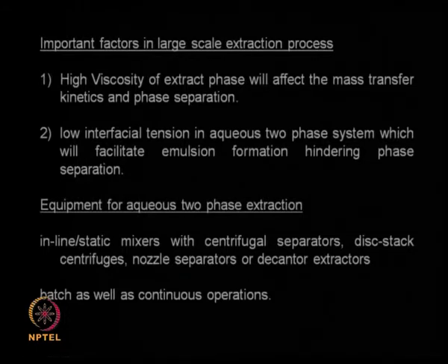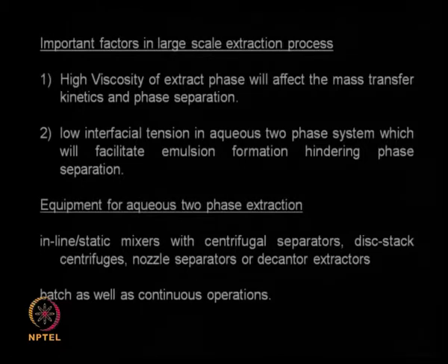So these two important points we need to consider when you are scaling up this type of aqueous two phase systems. So people have considered inline and static mixers, that means you will have long tubes filled with certain static elements, and when the two liquids flow through it, they get mixed, and hence during the mixing process extraction takes place.